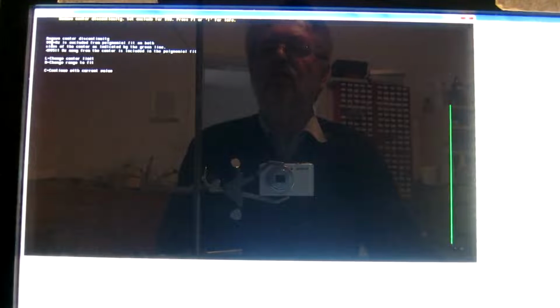from the center in both sides, but since the pulse repetition frequency is 700, I need to make this region a little bit bigger, because the filter that removes the DC in the procedure of calibration has a corner frequency a little bit higher than this. Let's make it, this is not very critical, but let's make it 4 kilohertz.